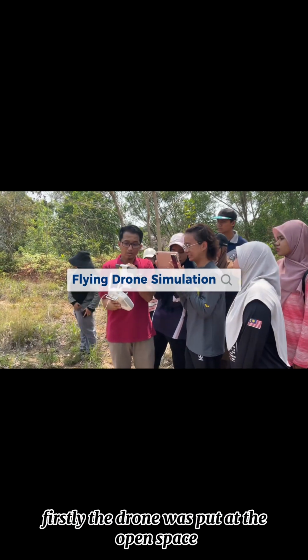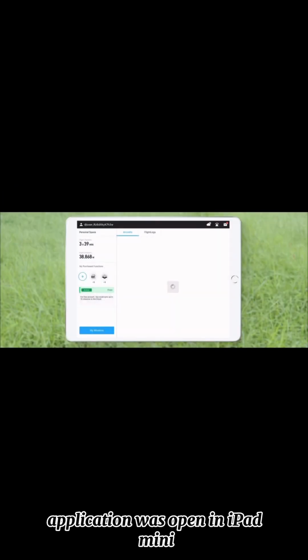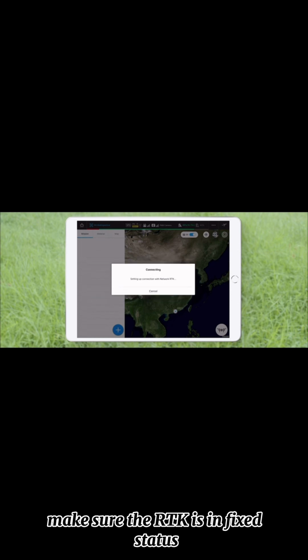Next, flying drone simulation. Firstly, the drone was put in an open space, far from any obstacles such as trees. Then, the DJI Ground Station Pro application was opened on an iPad mini. Tap to select an RTK positioning method. Make sure the RTK is in fixed status.